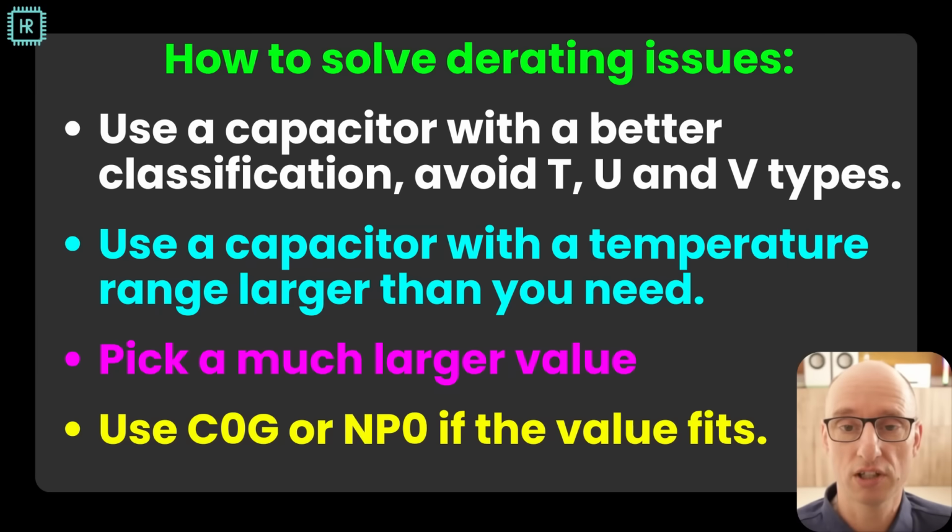You could also use a class 1 capacitor if the value is small enough and you're willing to pay for it. They are more expensive, but sometimes you absolutely need the stability of a class 1 capacitor because your circuit simply won't work without it. Now measuring this kind of reduction due to temperature is already bad, but the next effect I'm going to talk about has an even more devastating effect. I actually measured an 89% drop in capacitance while staying within datasheet operating conditions.